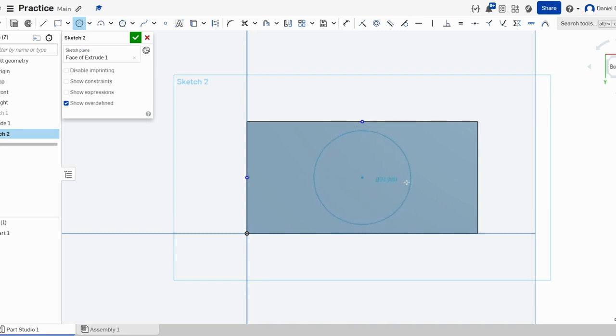So you can see that because this is a center point circle, it's going to fix that point, and I've already clicked and let go, and I'm just dragging and it makes my circle. When I'm ready to accept that circle, I can left click one more time. And again, I can dimension this. So let's say I want that hole to be exactly 10 millimeters. I'm just going to type in 10, and it's going to adjust that, and it's black now because it's constrained. So it has a dimension, and that dimension can't change unless we go in and change it.